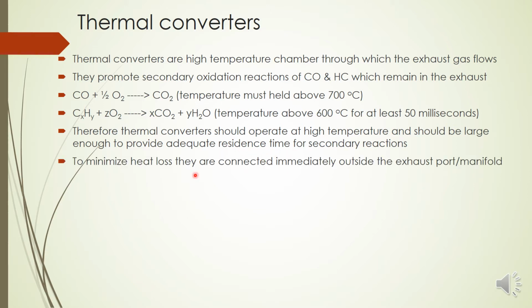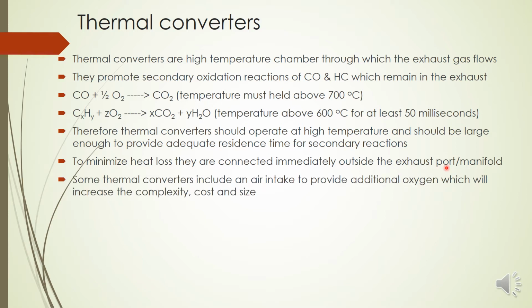Generally, to minimize the heat loss, they are connected immediately outside the exhaust port. So after the exhaust valve itself, in the exhaust manifold, this chamber can be connected. And some thermal converters also take in air from outside. We know that we require oxygen for all these reactions, and therefore some thermal converters take air from the outside atmosphere, but it will increase the size and complexity of this thermal converter.